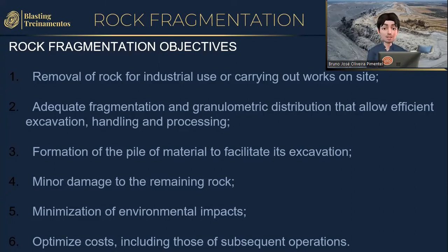So, I have to carry out my activity of breaking the rock, that is, fragmenting it to allow or facilitate its removal, but without damaging the rocks, structures and facilities that may be close to this block of rock that I need to remove. My fifth objective is to do this without generating environmental impacts. And we will see further on that during the use of explosives for rock fragmentation, that is, during our blasting, we are subject to causing environmental impacts. So, we want to minimize these impacts and whenever possible not cause any impact during our activities.